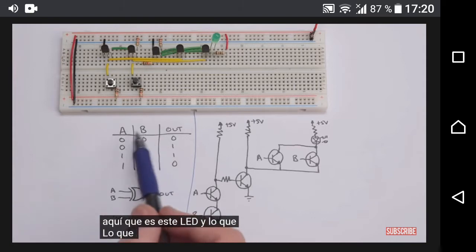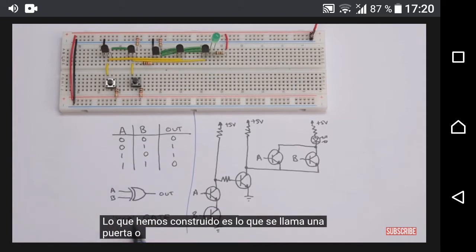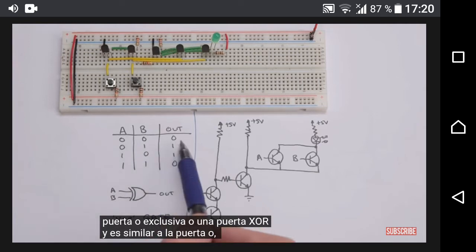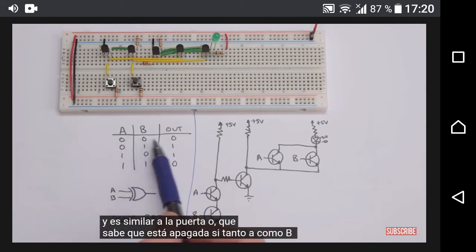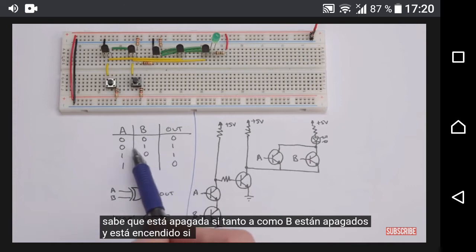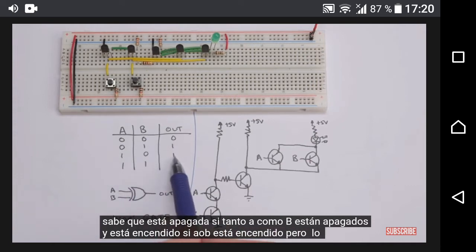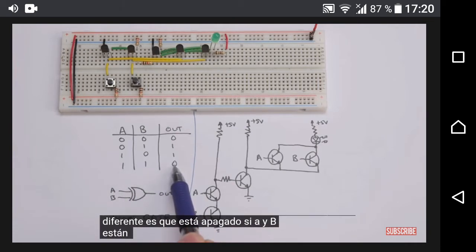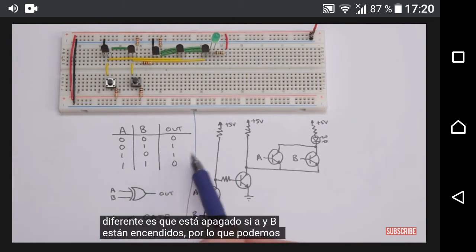And what we've built is what's called an exclusive OR gate, or an XOR gate, and it's similar to the OR gate, which is off if both A and B are off, and it's on if A or B is on. But what's different is that it's off if A and B are on. And so we can actually see that operation.